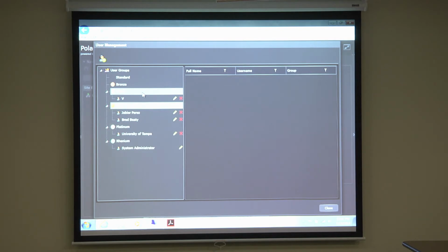For example, this is room 101. Then the aux sensor will be named OCS room 101. So in his system, he'll see the sensor and what room, because he sees the name, so he knows that sensor belongs to this room. So he can link that sensor in his front end to the VAV for that room, for example. All that is done via BACnet, and it exports all the points, and he pulls it, he discovers it, and then he does his stuff on his side. As far as his level, he wouldn't necessarily be programming it. He doesn't even need this. This exports it. So he pulls it and then goes into his BACnet program.